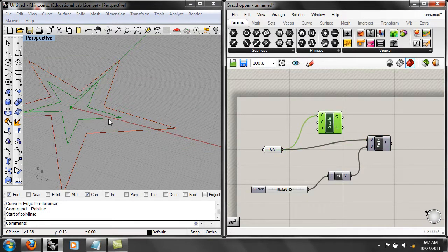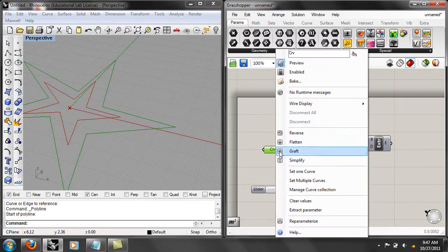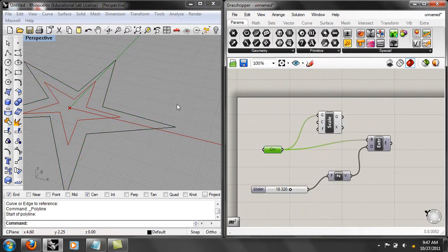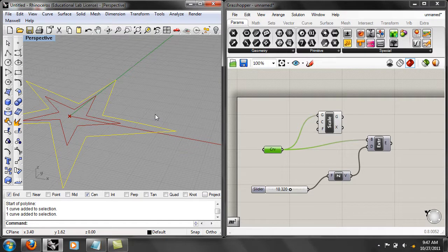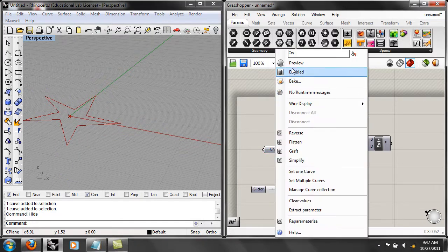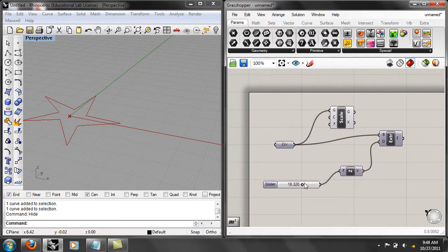They're all there in the sketch unless I turn off the preview. If I disable them, that's the Rhino one that's underneath it. We can hide that too. Just press hide. Again, I can turn on preview and turn off preview for that. So the scaled one is this one. It's 0.5 of the original geometry. Okay, and let's put a slider in there.